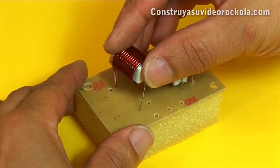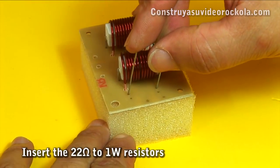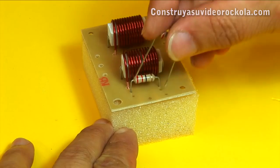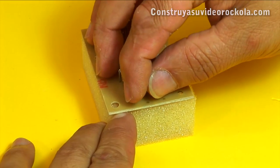We put the other set. Now place the 22 ohm resistors in their respective place. Remember that as the resistors are connected in parallel, they become a single resistor, of 11 ohms at 2 watts.